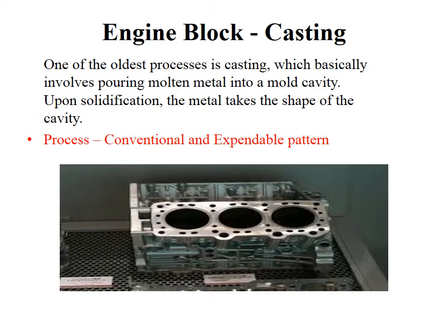So first, talking about the engine block. You know that the engine block is the major component in an engine, which gives the space for fixing up the cylinder head, valves, and where the piston is connected to the connecting rod, so that serves as a base component, and that is manufactured by using casting.